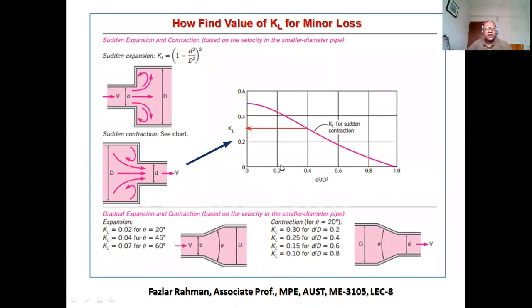Now, right over here, you see expansion and contraction is happening at the surface. That angle is 90 degrees. It produces a little bit more head loss. So instead, you can use gradually increasing or gradually shrinking. Like over here, your fluid is coming from the left side, and gradually right over here, the diameter is gradually increasing. So we put some angle.